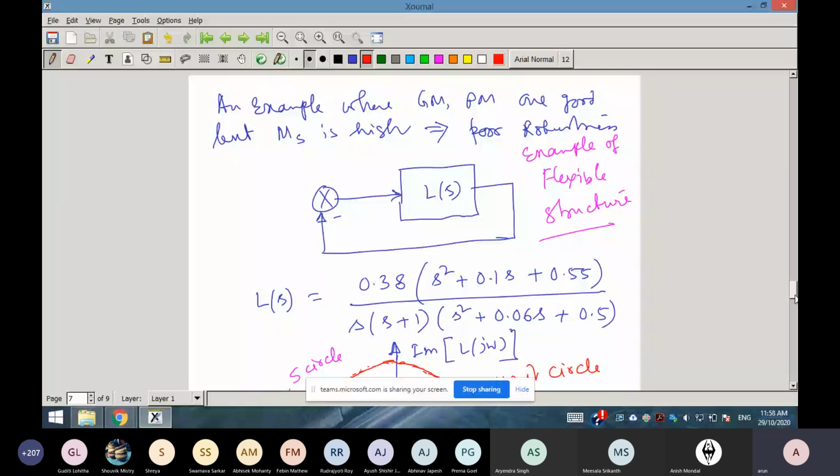For Nyquist plot, for gain margin, for drawing root locus, do you need any reference input or output? You do not, right? For Nyquist plot, root locus, all these things, to draw them you only need G(s) into C(s), the loop transfer function. But you will break the loop and obtain the loop transfer function. Got it?